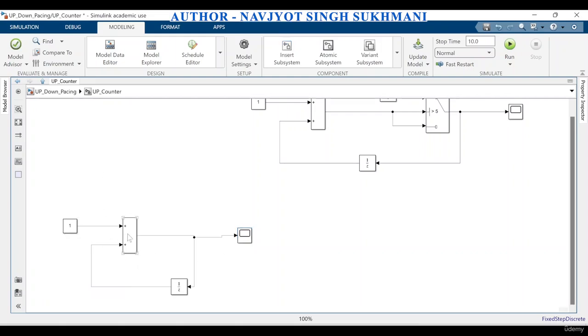In the first step I'll have input 1 at the sample time. At the first sample, at 0, this delay doesn't have anything, but this has 1, and this 1 should come here, and it came here. At the second sample time, this 1 came here and this 1 came here, so 1 plus 1 becomes 2, then the output should be 2 on the scope, and again the unit delay block is holding a 2. At the next sample time, that 2 will go up and this 1 will come there, and again 3 will come as an output. So we will see how it works.